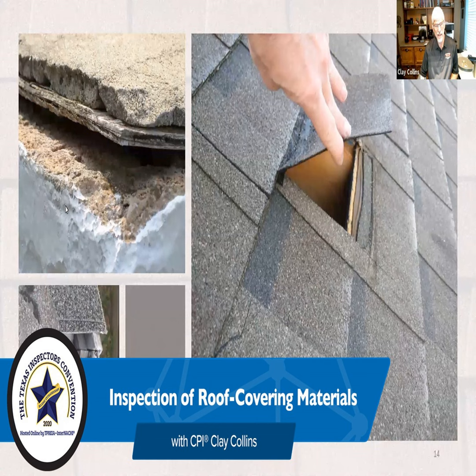Temperature, insulation, and ventilation. We talked about the insulation against the roof deck, and that would include insulated boards. It would include insulation boards placed between rafters, and it would include the spray foam. And as far as I'm concerned, it would include the radiant barrier, whether it is the radiant barrier deck or the radiant barrier installed post-construction. If that is installed improperly, that roof cover may overheat.